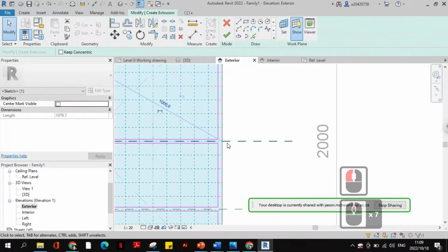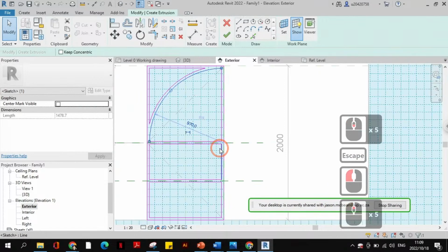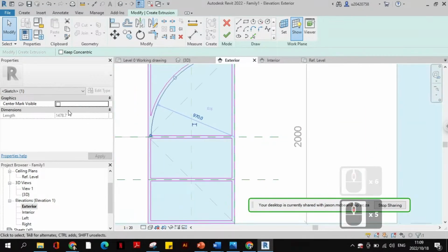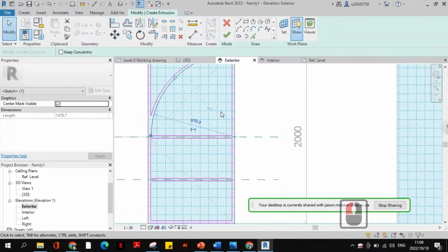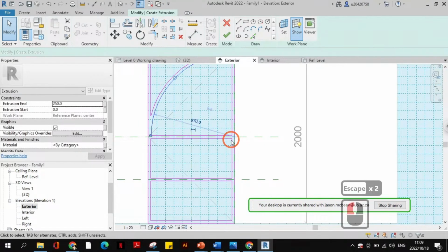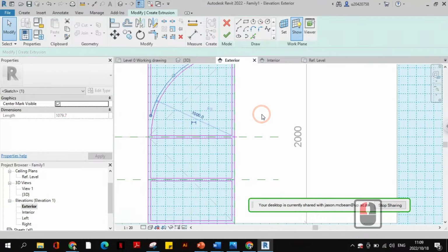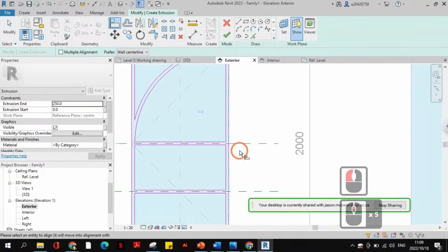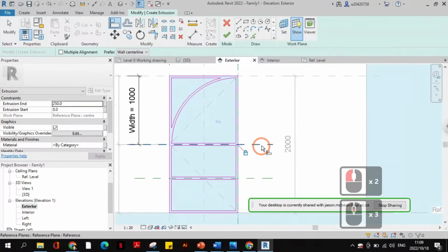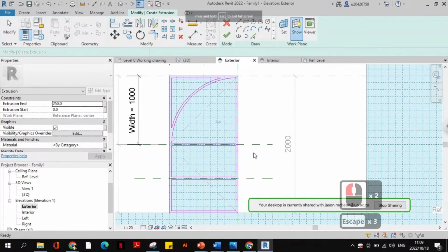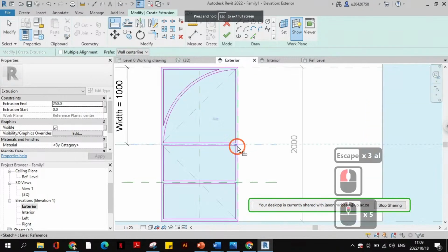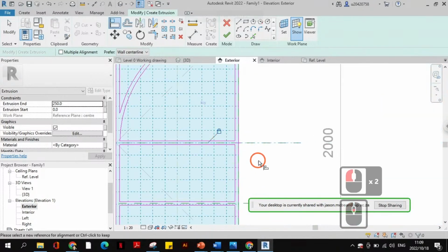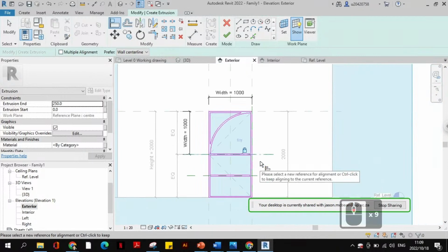Now, here's the little catch. This thing always needs to be locked because technically, the center's always there. Now, this is where all hell breaks loose. You click on an arc and you tell it show center mark. It's very strange. And then you make sure that you lock in a line. It just means that if you align that and that center mark, it forces this relationship.